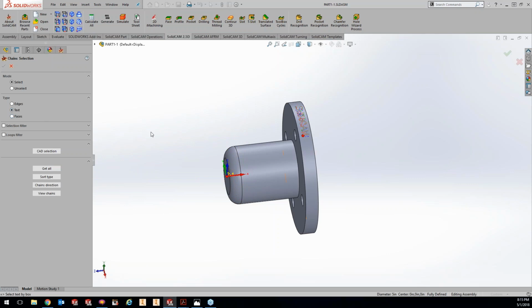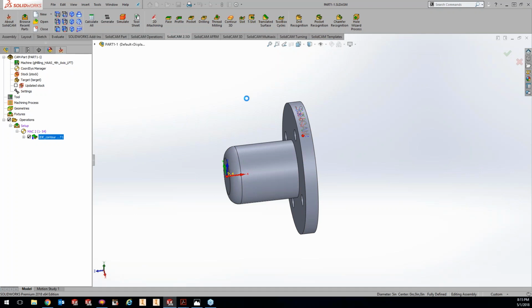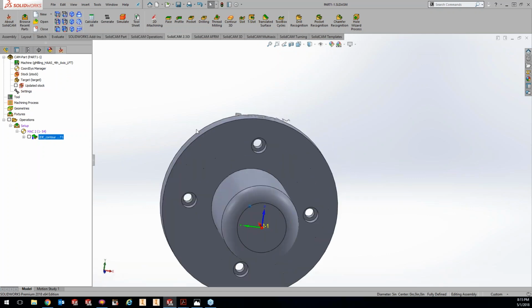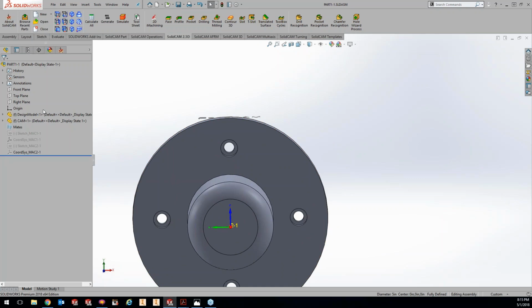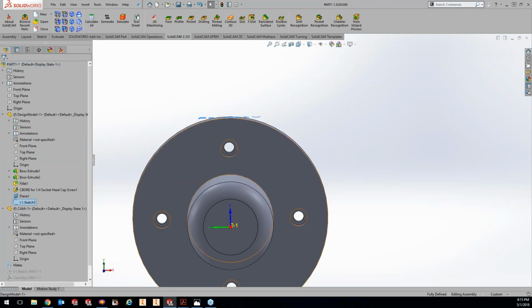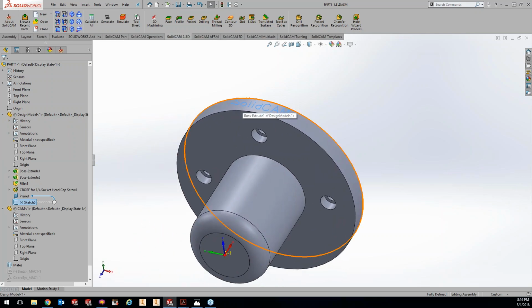Oh, yeah. Okay. Great. So text flat, yeah, I'll show you. So I'll turn off the toolpath here. So Ronnie, if you look down straight on, see how my sketch geometry is flat? When I created this one, I just created a plane above the part right here with this plane. And so I just threw that geometry on there. So what Greg's getting at is the text isn't physically wrapped on the model itself.